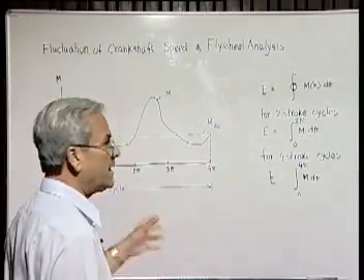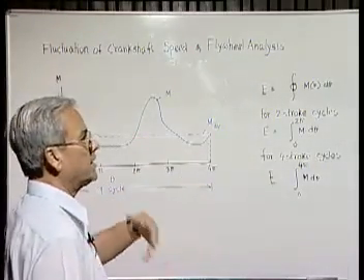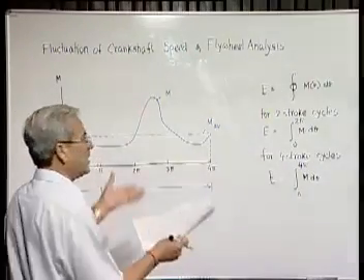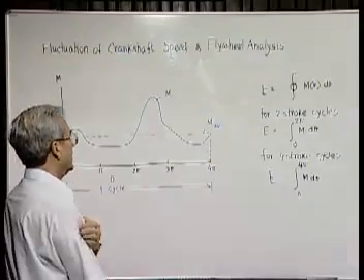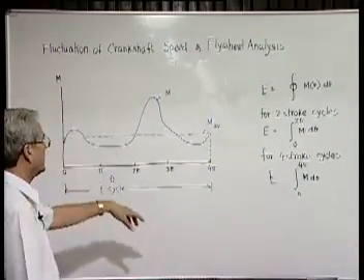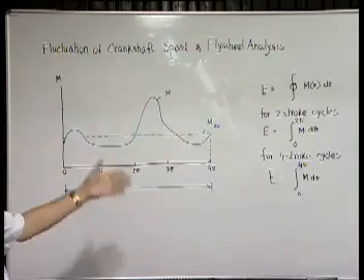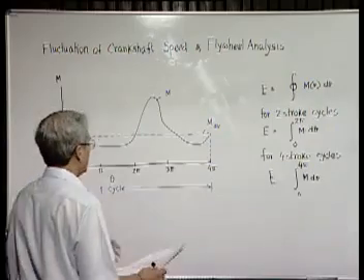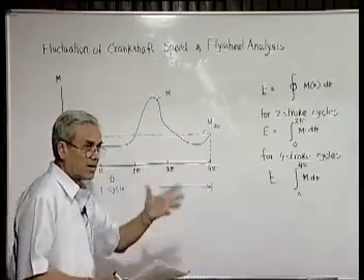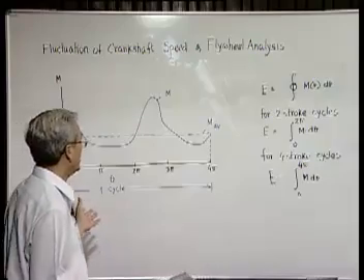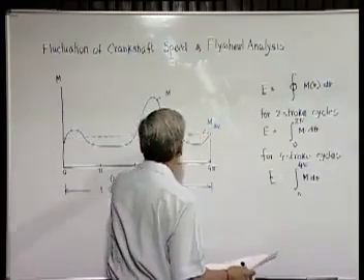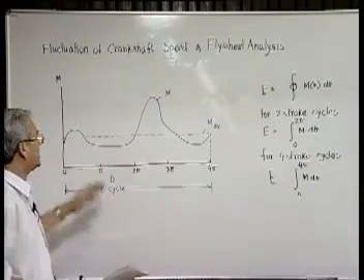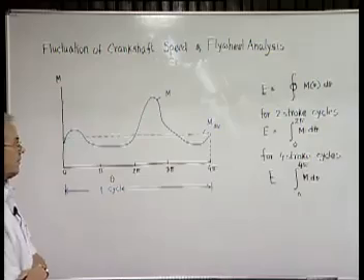And obviously, in steady state, we assume the same amount of energy is utilized, so that there is no accumulation of energy in the engine continuously changing its speed. In case of starting, either it increases, or when it is less than the power utilized at the output end, then it will gradually go down. So in steady state operation, the resisting torque, which we have assumed constant in this particular situation, must be equal to the value such that the total work consumed by the load is the same as the total energy produced in every cycle.